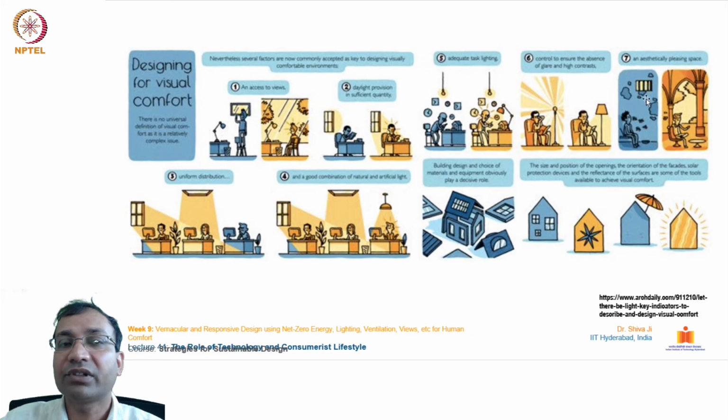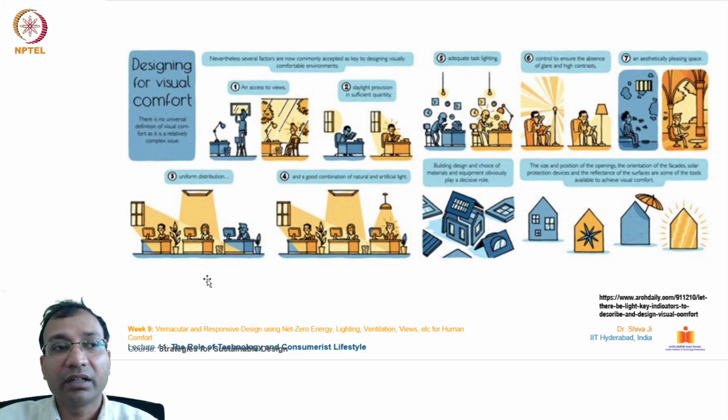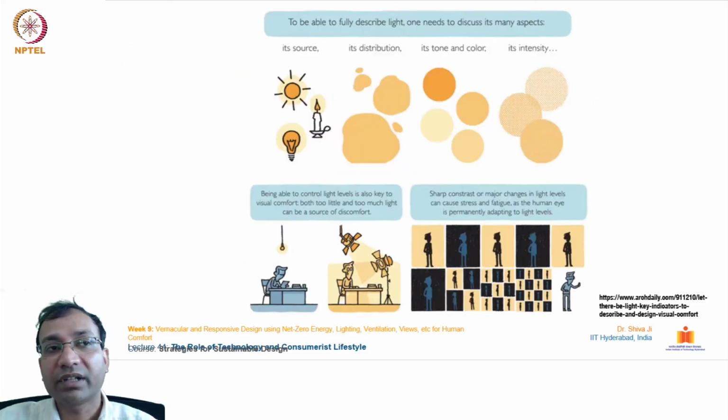You can see in these illustrations a person who is confined inside a space, a person who is sitting outside, and a space where some workstations are lit and some are not properly lit, creating an imbalance. So we must take care of such workstations, where natural light cannot reach deeper, creating a balanced approach. Similarly, what parts of the building, what components and surfaces of the building, should have how much proportion as an opening, that also should be thought of. That is the overall objective to understand from here.